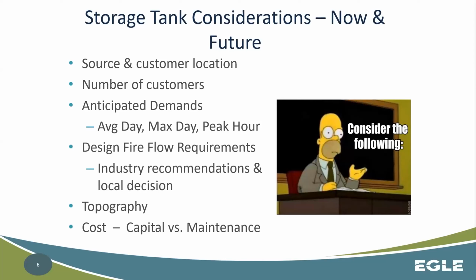What's your usual demand of water? And then also design for fire flow. Again, maybe industry demands or wants you to have larger capacity, larger storage, because they have a potentially flammable product that they're producing. So it's trying to meet their goals, whatever that situation might be, rather than just, okay, we have a hydrant because this is a residential area. You might need more fire flow if you have large industrial complexes, things like that.